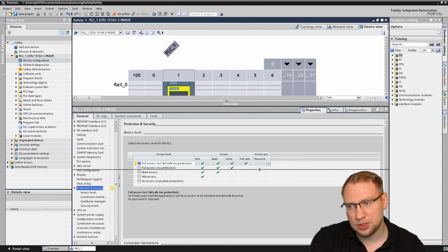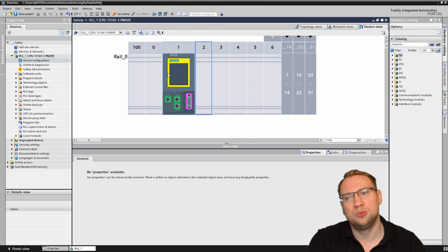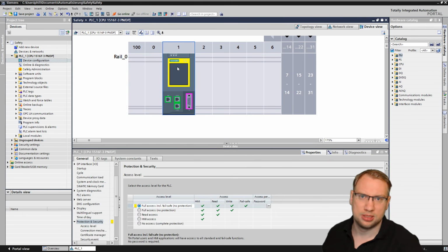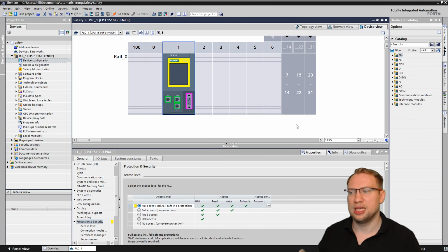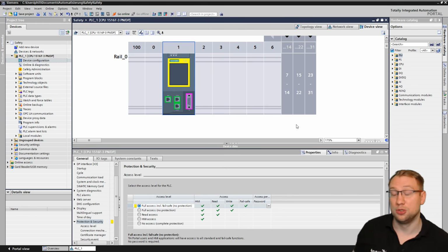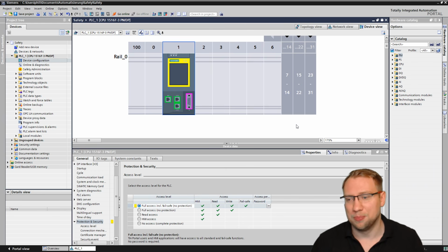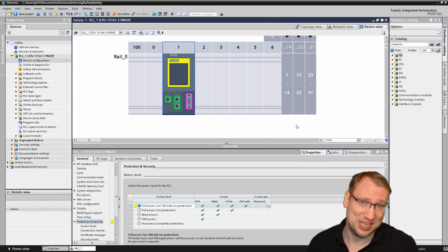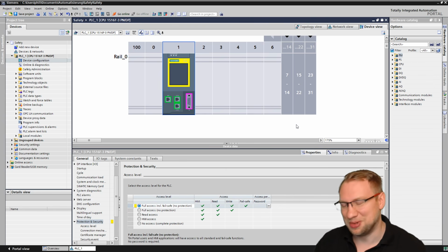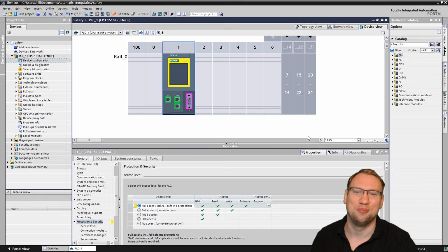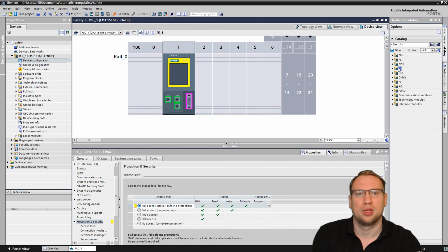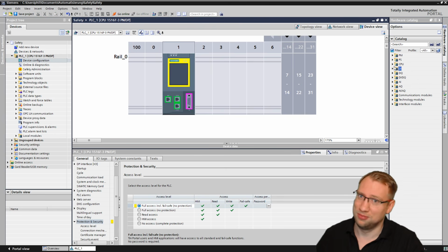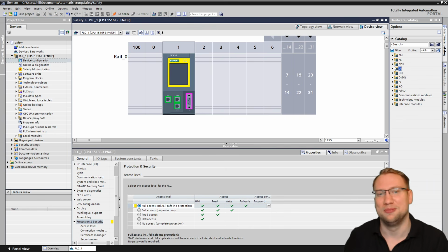Next, we don't really need to set anything in the PLC except for the activation. There's also some addressing, PROFIsafe addressing, which I'm not going to dive into because I'm also not an expert. There's no need to change the PROFIsafe addressing usually because that's internal for safety communication. Try not touching it. If you need to touch it, you're probably more of an expert in the field.